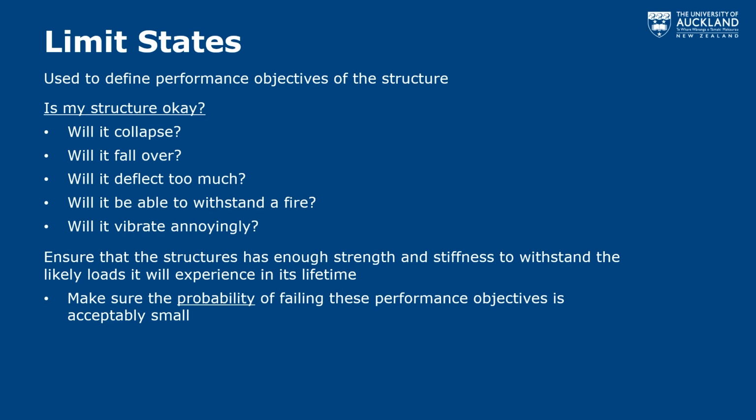So these are the performance objectives that we want to define for a building, and we will broadly lump those together in what we call these limit states. And with these limit states, this helps make sure that we have some set criteria to design to, and then we can adjust the loading and the demands to be reflective of what the consequence of those failures are at these different limit states.